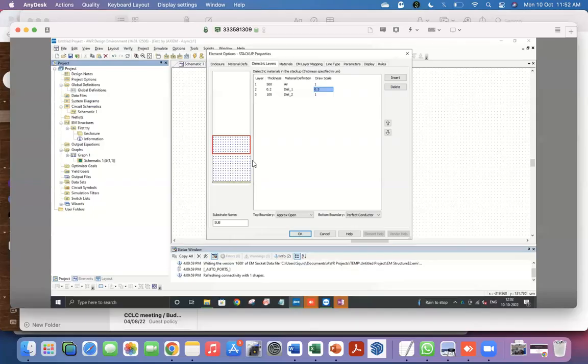No, right now we are not talking about what signals we are providing or anything. We are talking about the structure, and we have specifically been discussing transmission lines. So we will make transmission lines here. What you are looking at represents the cross section of the circuit board on which the transmission line is going to exist. So what do you need to make a planar transmission line? You need some ground plane, some dielectric material, and some metallic patterns on the top. That's what we are defining. There are no signals yet; we come to that.